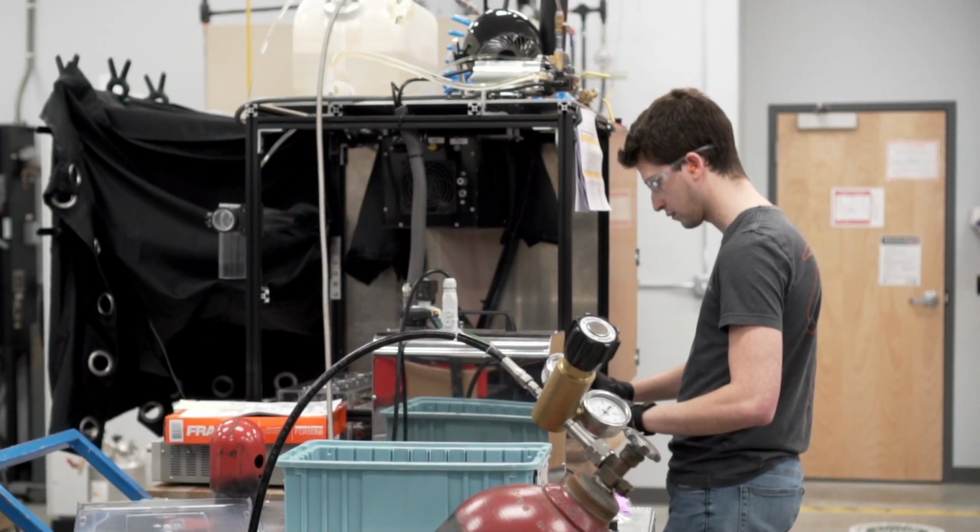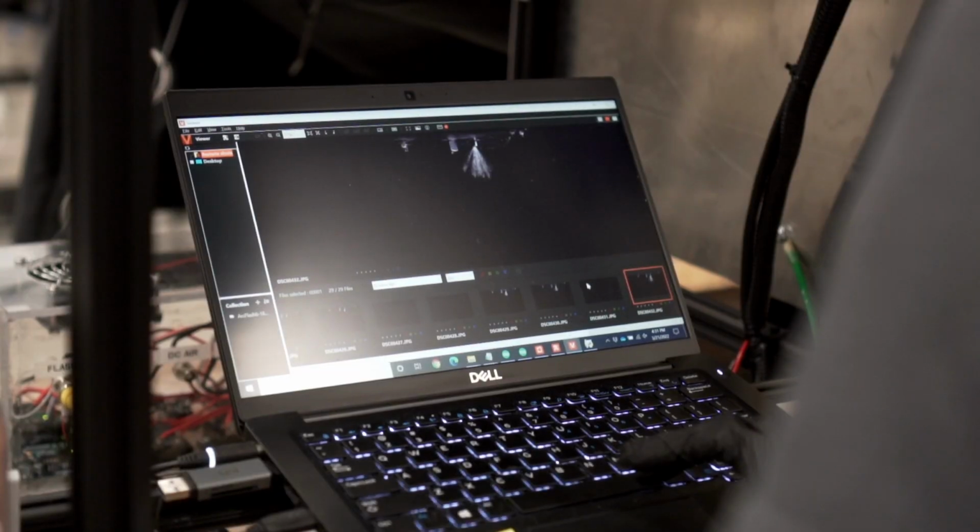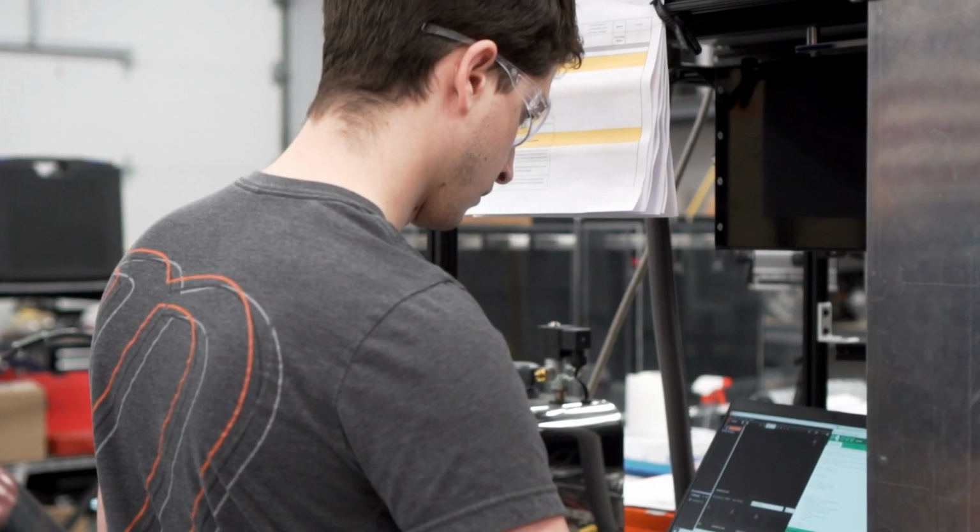This means that the spray pattern is specific for each application, and it will result in the better interaction between the fuel injected and the airflow in the intake ports for the PFI injector or inside the combustion chamber for a DI injector. This will result in a better fuel mixture formation, higher quality of combustion, and higher efficiencies.